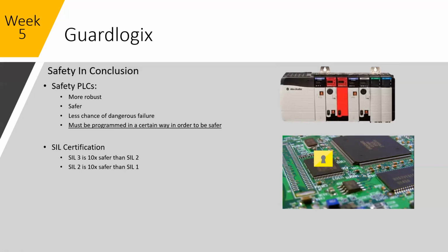And then with the SIL, the safety integrity level certification, SIL3 is 10 times safer than SIL2. SIL2, 10 times safer than SIL1. Any questions on SIL? GuardLogix? Has anybody dealt with, seen these? No.